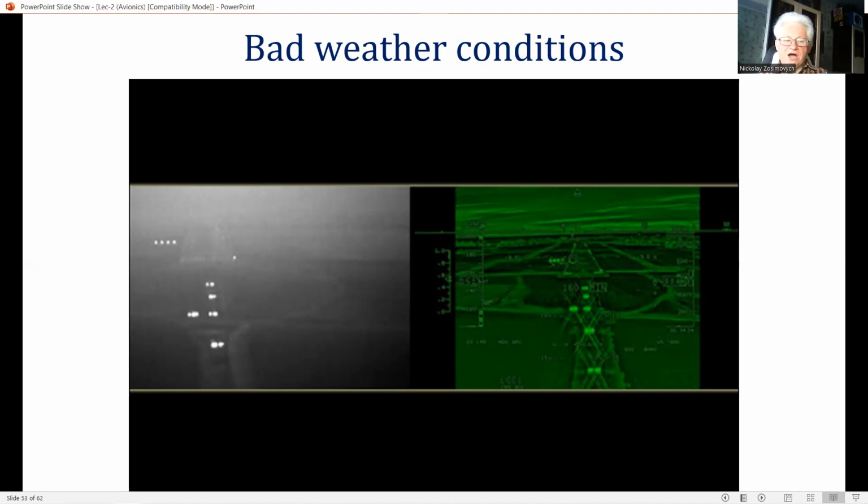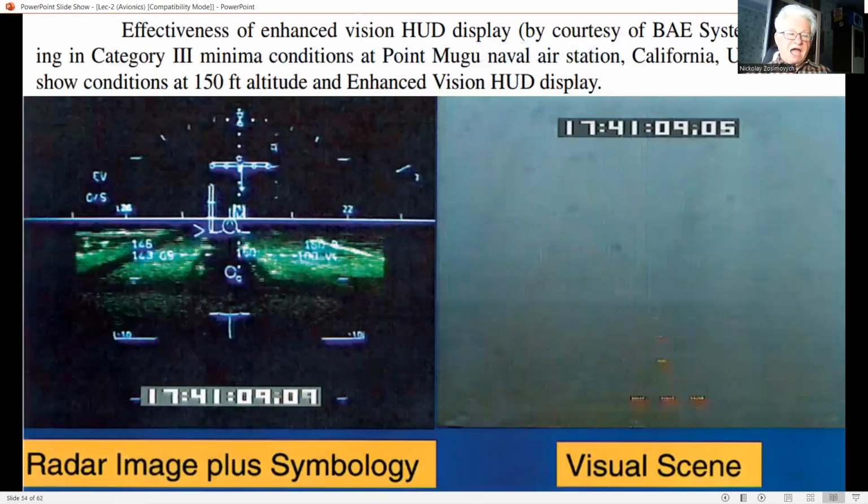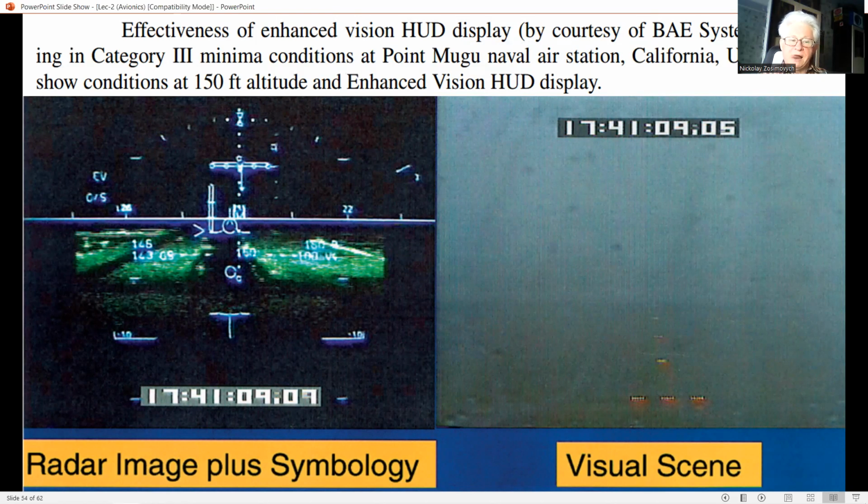The display of aircraft velocity vector on the HUD was found to be particularly helpful throughout the approach when used in conjunction with the electronic image of the outside world, and enabled the control of the aircraft's flight path to be precisely matched. The evaluation pilots reported Cooper Harper ratings of 3, satisfactory without improvement, with minimal compensation required of the pilot for desired performance.